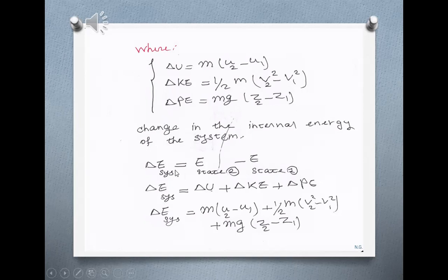So I just explained the right side of the energy balance equation. There is a system. The system can be a pipe, it can be a duct, it can be anything. Just look at it as a black box, with some energy transfer into the system and some energy transfer out of the system. The difference between these two, if they don't balance, is the change of energy of the system, according to conservation of energy, because energy cannot be created or destroyed.